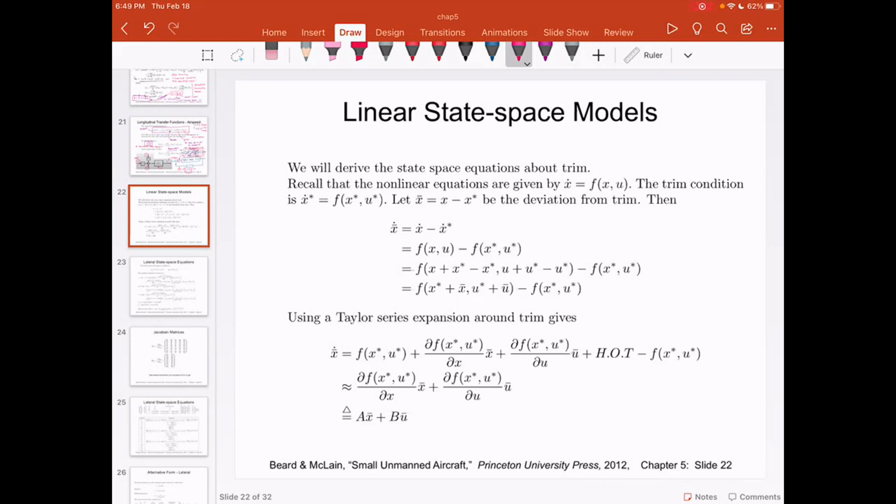And since this is a linear control, the domain of operation, which means where these controls are applicable, will be limited. But you'll be surprised that the range is quite big. So what we will do in the subsequent project is design these control loops and integrate them in our simulation, so that we change the value of VA. If you change the wind speed or the wind gust parameter, the aircraft will be in stable level flight on its own. Does that make sense?